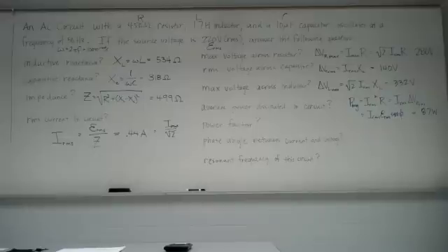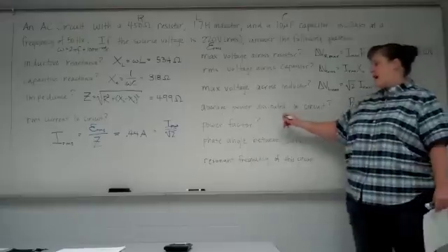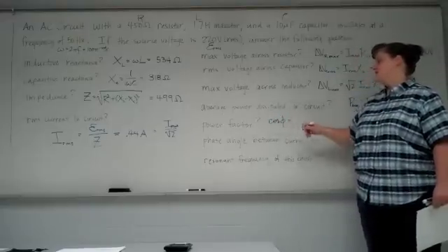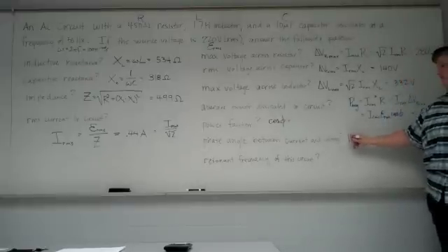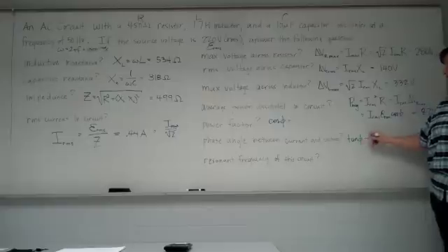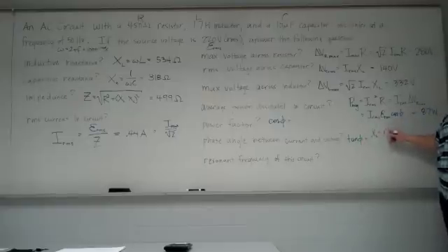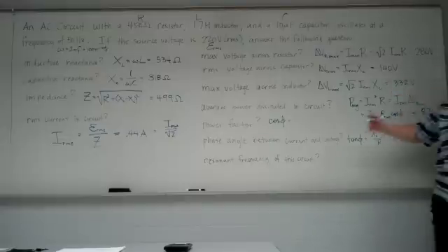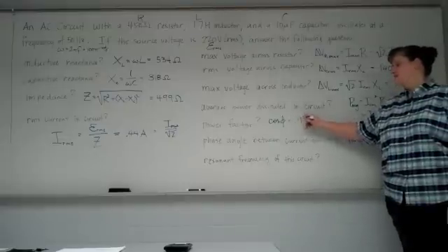It doesn't matter which equation you use, as long as you're, of course, plugging in the correct values for any of them. The power factor is the cosine of phi. Either we can go ahead and do the second question first. Tangent of phi is XL minus XC over R. We know XL, we know XC, we know R. Take the inverse tangent. We find that phi is 25.6 degrees. We take the cosine of it, we'll have the power factor.